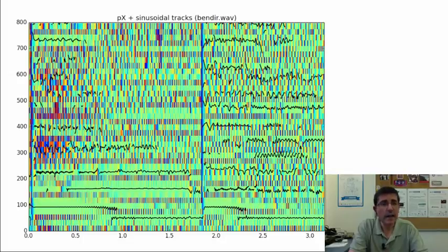And also we can look at the same tracks in the phase spectrum. If we take the phase spectrogram, which is the derivative of the phase, and we plot those black lines, the frequency tracks, on top of that, we get this result. It's quite interesting because clearly we see that the black tracks are in the places where the color is clear, and these are the locations where the phase changes less, where there is more phase continuity. So this indicates that the phase information would also be quite relevant in tracking these sinusoids, because the phase information allows us to distinguish this variability and stability aspect of a given partial.